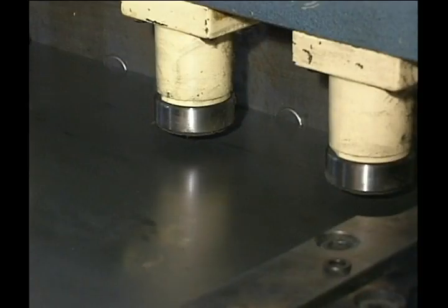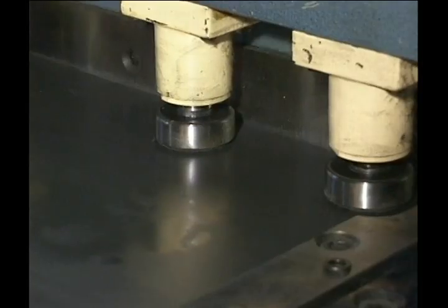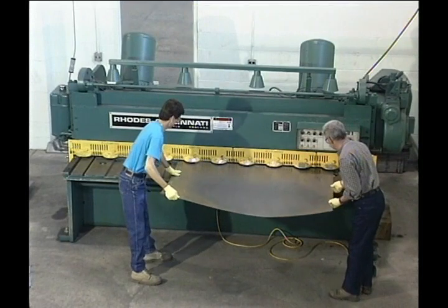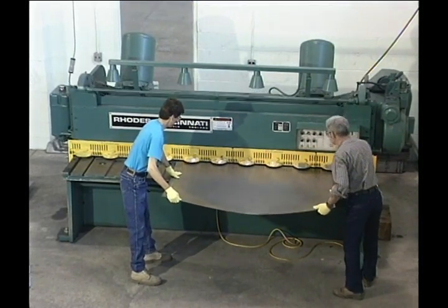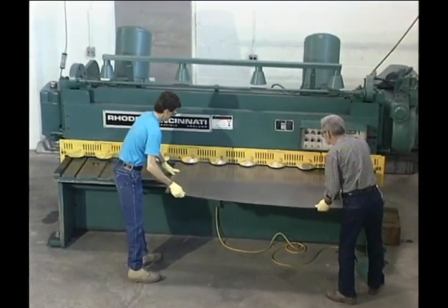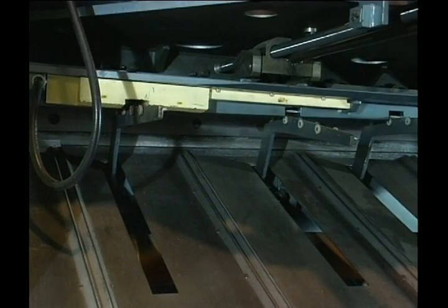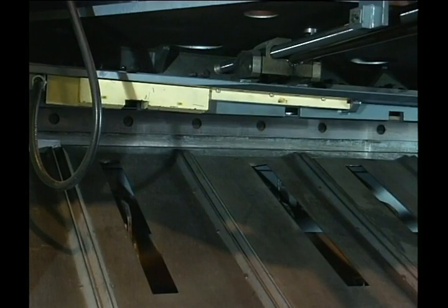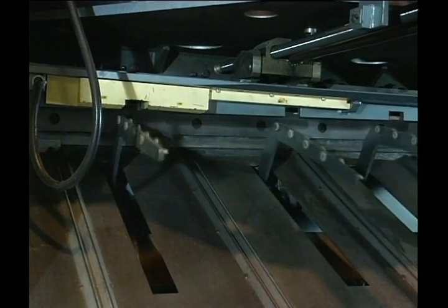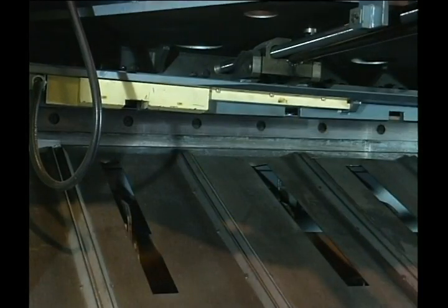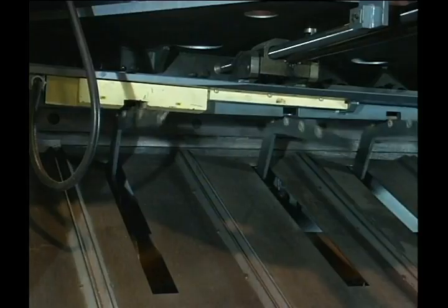For rapid, accurate cutting, electronic sensors in the back gauge automatically start the shearing process only when the stock is in the correct position. When the back gauge is used to shear wide drops of thin metal, the material often sags, causing an inaccurate measurement. To eliminate this problem, a sheet support system can be added to the back of a shear. Generally, a sheet support holds the workpiece in a horizontal plane until it is cut. The support then pivots down, permitting the workpiece to drop.